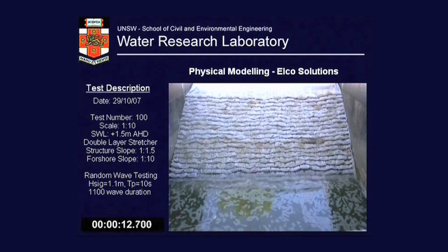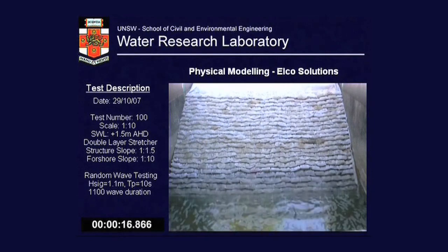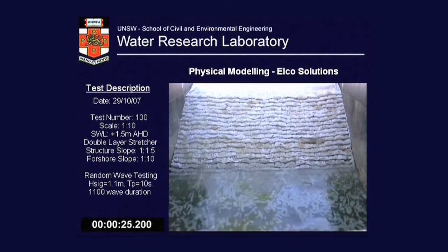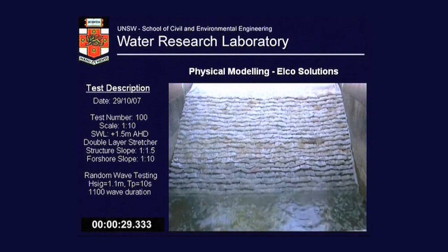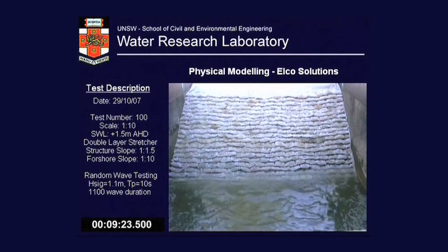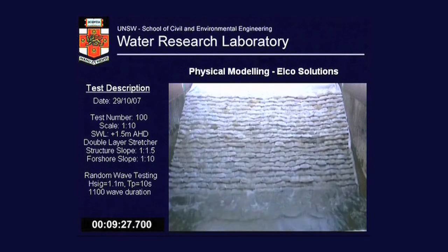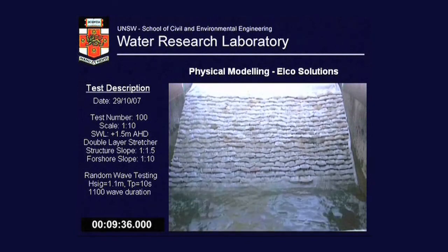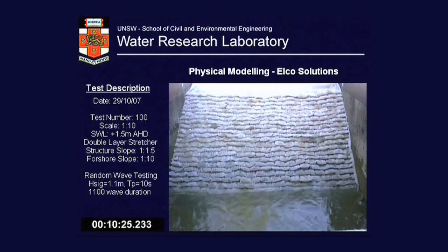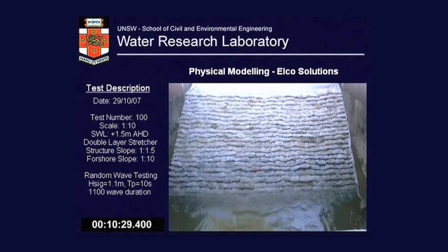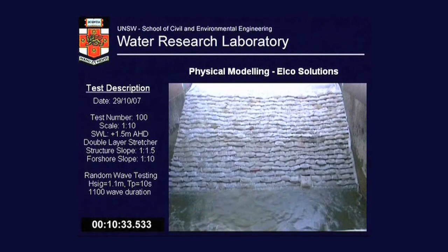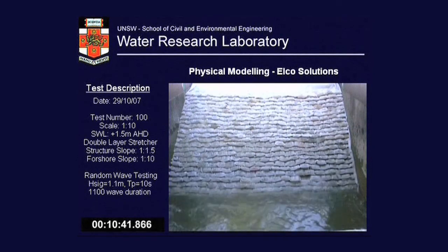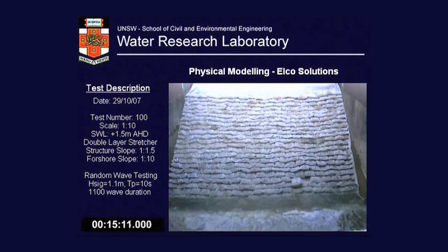Right, so these are waves. This is about a 1 in 10 scale of model testing. And you'll see, if you look, damage is starting to initiate around here. You can see we have lost a container down the bottom there as well. So nearly all the damage occurs within the waterline. Obviously you don't get damage up here, but basically above and below the mean sea level. This is equivalent to about 1 to 2 hours of real world testing.